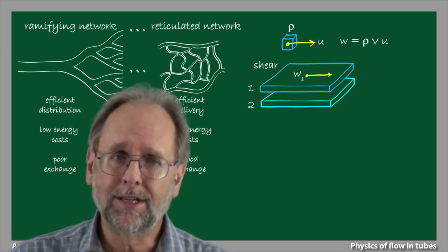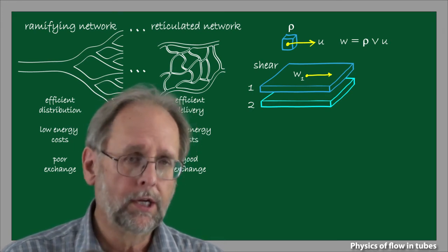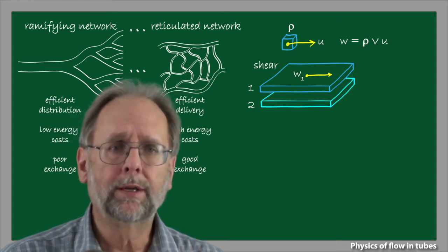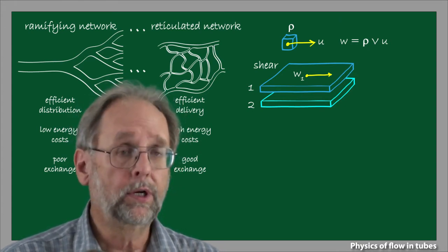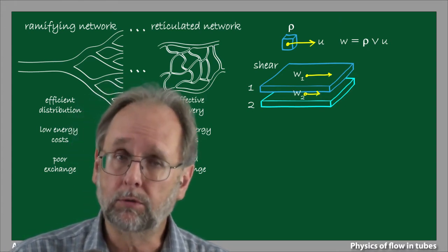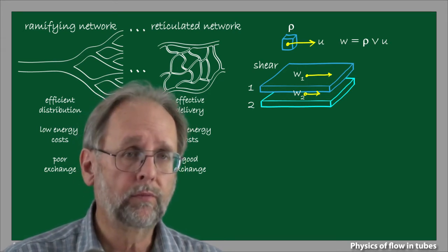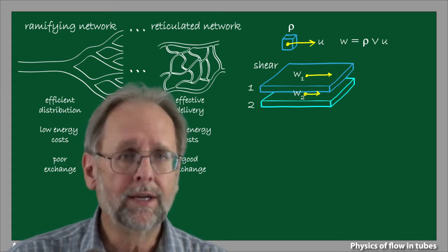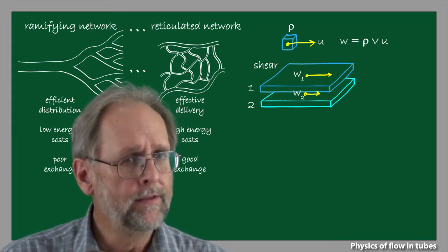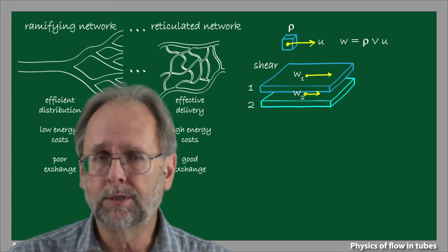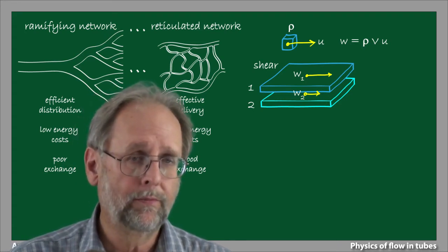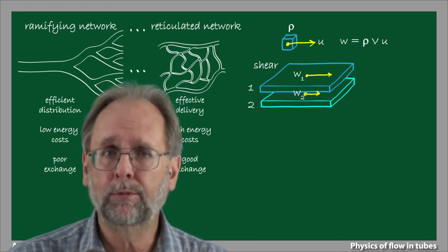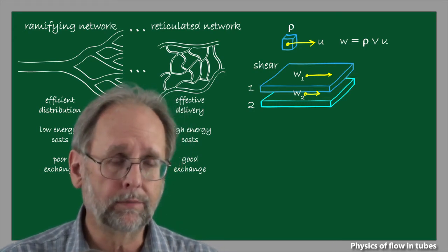Imagine now that there exists a kind of frictional force between parcel 1 and parcel 2. The shearing motion in parcel 1 will therefore impart some of its momentum to parcel 2, setting it in motion too. This transfer of momentum in fluids has a special name, viscosity. This example makes two important points about what viscosity is. The first is that viscosity is fundamentally a transfer of momentum within fluids subject to shear.